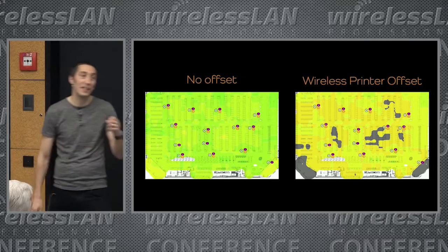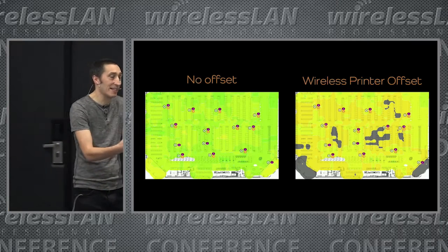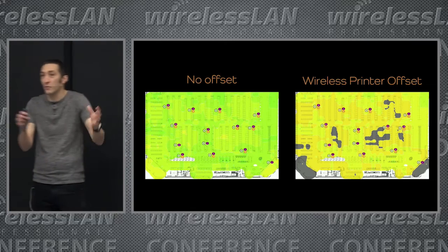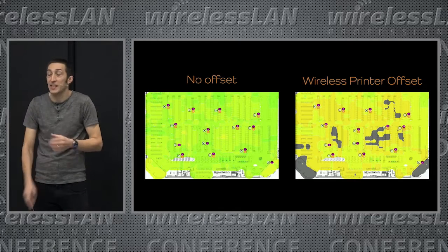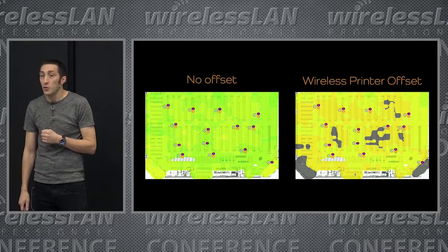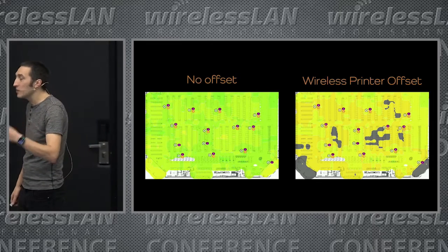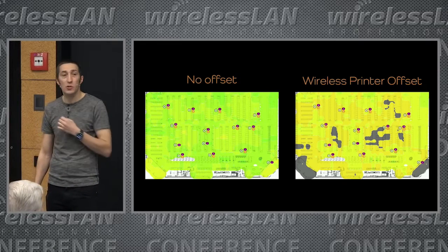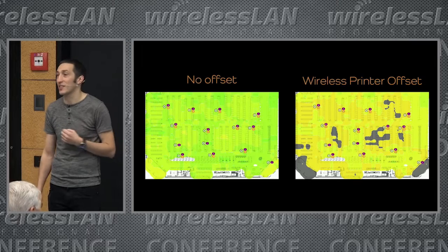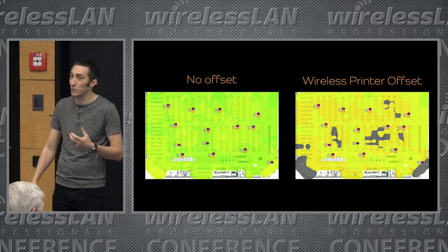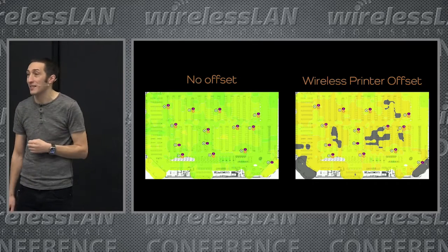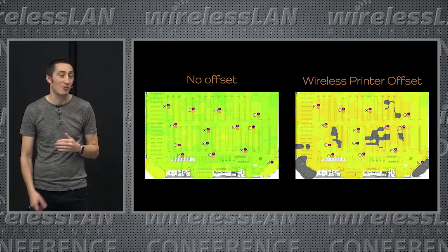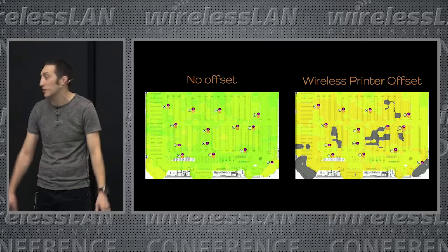And in that case, I think that is valid because you're not assessing against the design, you're assessing against, do I have enough coverage for this particular device to work? You may even do that in your validations, but just do it for you. I would never send that to the customer, okay? Because it can confuse them. As I say, maybe the grey is actually okay. Because, yeah, I'm below my primary signal strength, but I expect the printer to be, and actually it'll still work okay.